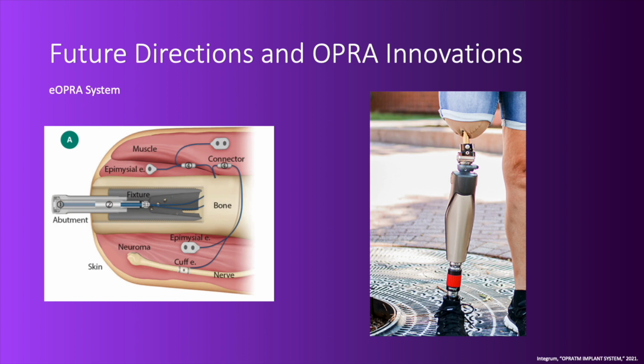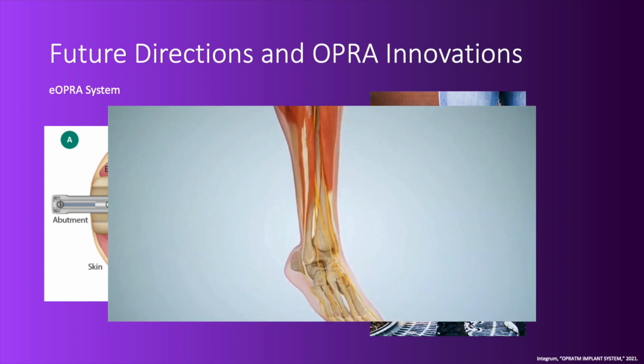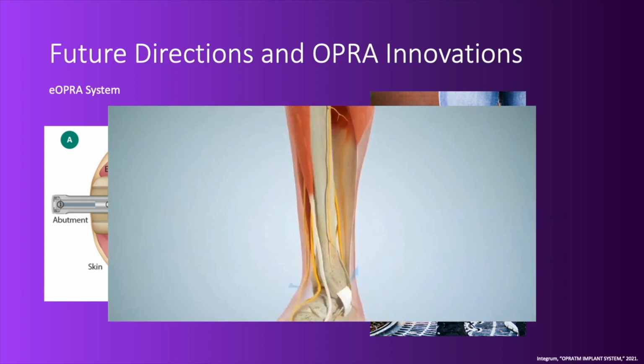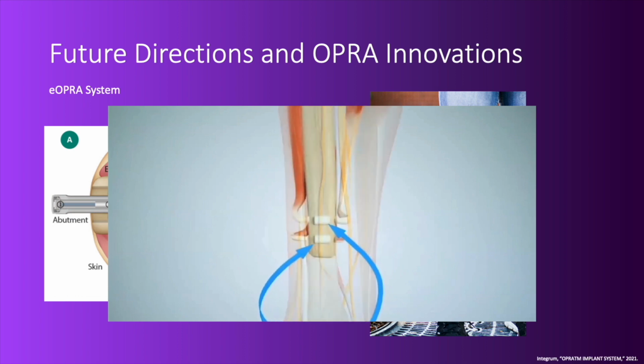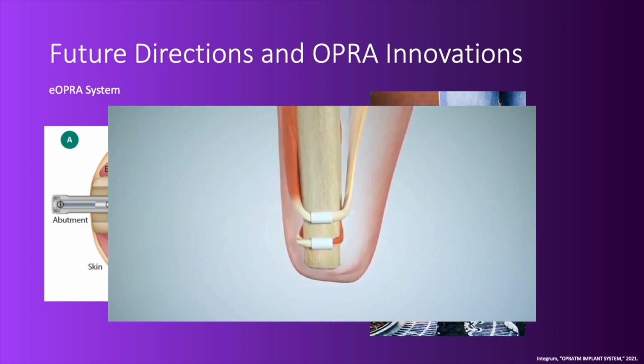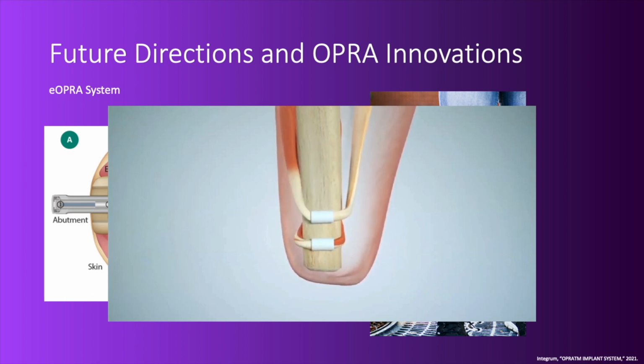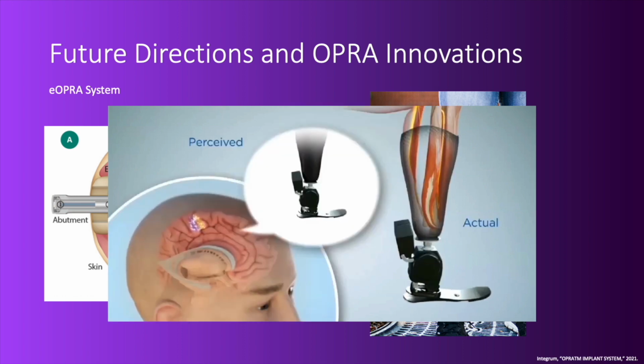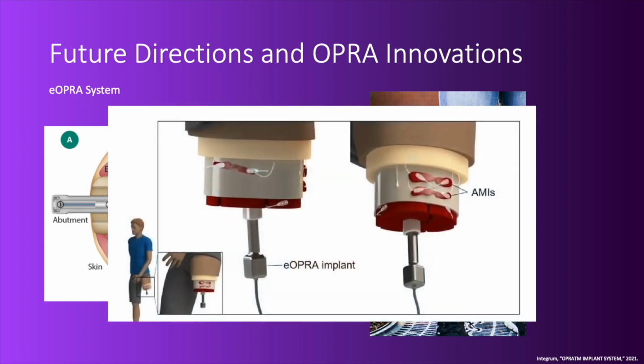transfemoral prosthetic. This particular design of implant is particularly unique, as the combination of implanted EMG paired with nerve medialization results in phantom limb proprioception, where the implant can actually be recognized and perceived by the brain using the AMI, or agonist-antagonist myoneural interface. This also results in the ability for the user to control the knee and ankle power joints discreetly, instead of relying on a motion couple or exterior sensor arrangement for pseudo-control of the actuated prosthetic.